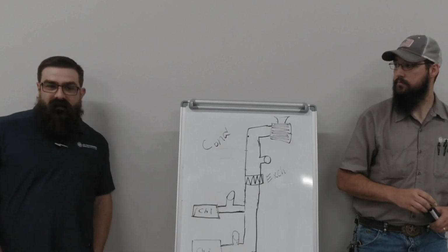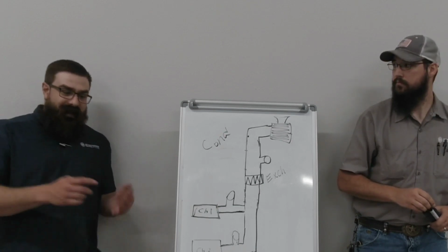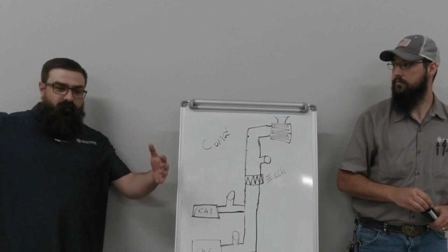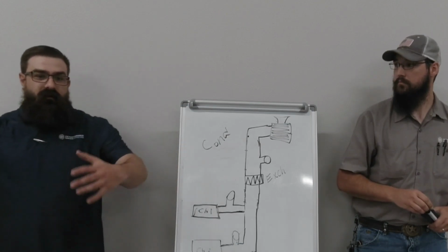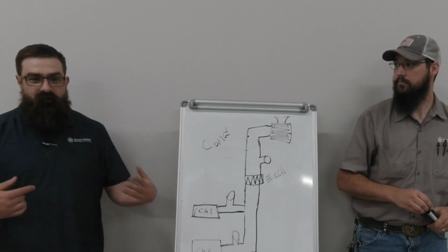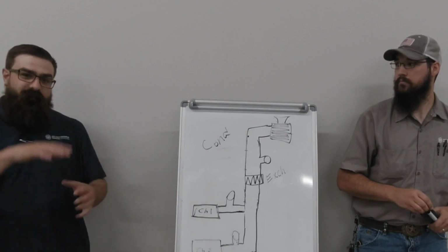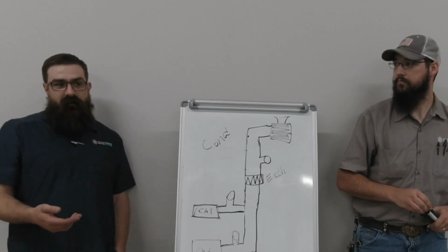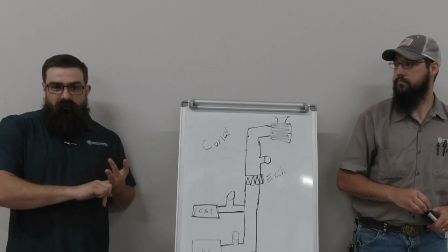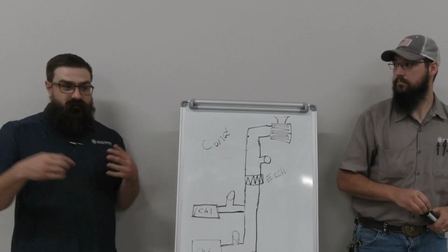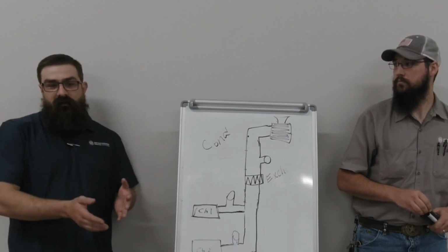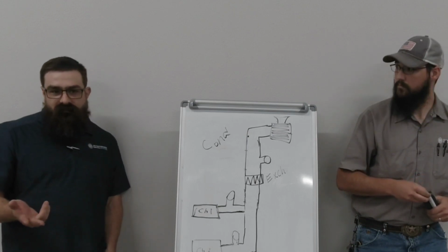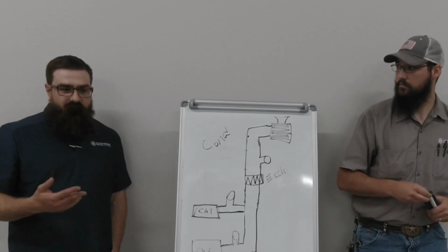They have a thermal storage tank there, and thermal storage tanks can be done with ice. It can just be really cold water, whatever. You basically cool this giant pool of water, and then you can mix that with the warmer water throughout the day to create a constant, a little bit higher temperature. And then they push that through heat exchangers, or like Domain 3 and 4 don't have heat exchangers. They use their chilled water straight to their equipment. But I think 7 and 8 have heat exchangers. A couple of them have heat exchangers.